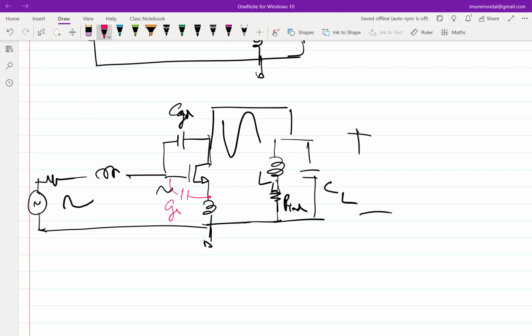So that's a problem. Another problem: if you recall, when we were discussing transceiver architectures, we talked about LNA is followed generally by a mixer. There will be switching in the mixer, and there can be coupling between mixer and the input of the LNA, which causes LO feed through and all those things. If you don't remember, go back to one of the initial lectures to figure out. And that feed through generally should happen through CGD. That is the only way this becomes a bilateral device, right? So a lot of issues with CGD.